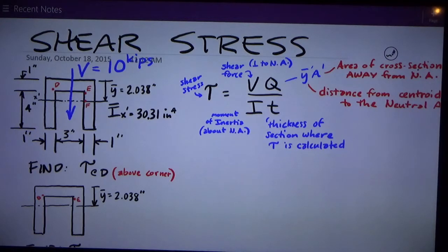Okay, so what we're dealing with is shear stress, transverse shear stress. Remember that shear is a force that's parallel to a surface, so it's parallel to this cut. And this transverse shear is a phenomenon that exists in beams due to bending. And it's a very important force and stress to design for, so we need to understand it. And it's got a lot of geometry in it.